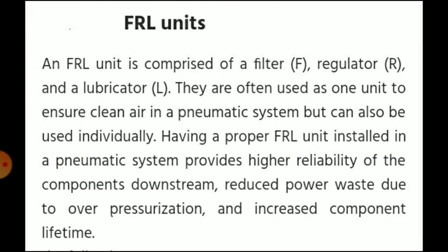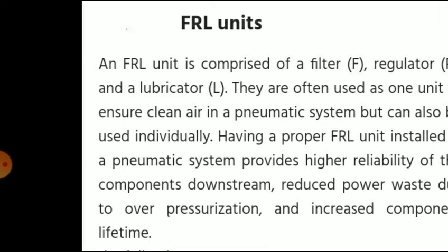An FRL unit is comprised of a filter, regulator, and lubricator. They are often used as one unit to ensure clean air in a pneumatic system, but can also be used individually. Having a proper FRL unit installed in a pneumatic system provides higher reliability of the components downstream, reduces power waste due to over pressurization, and increases component lifetime.